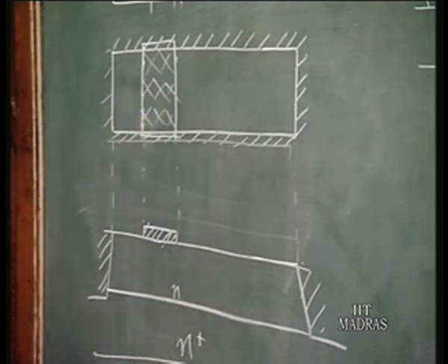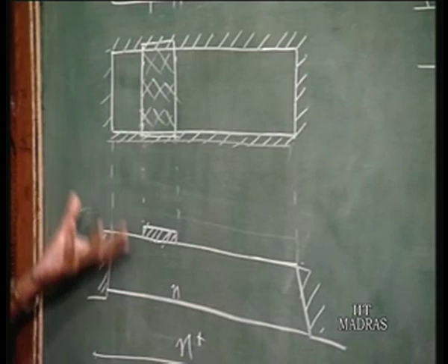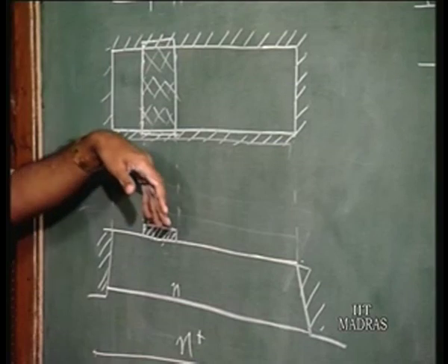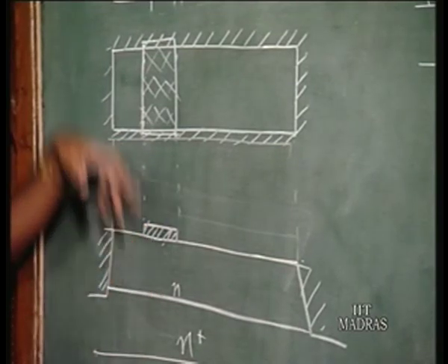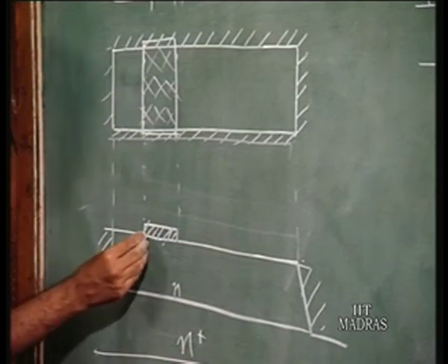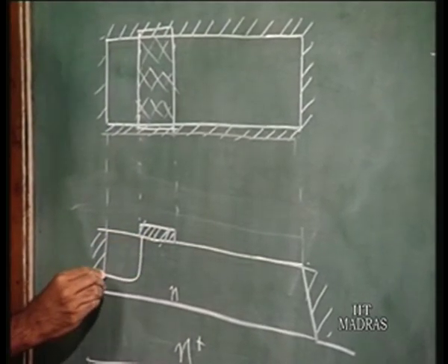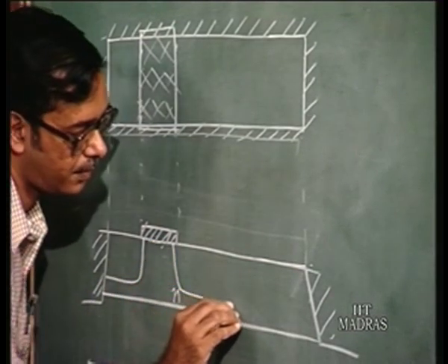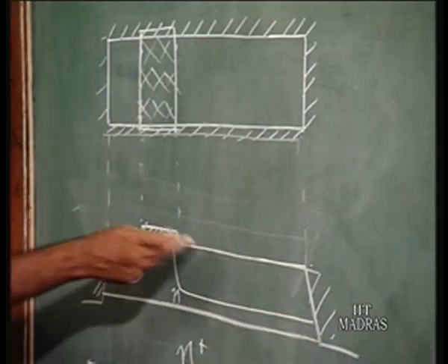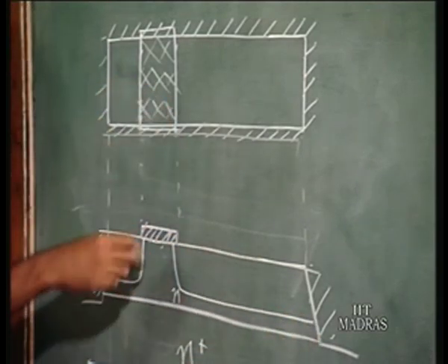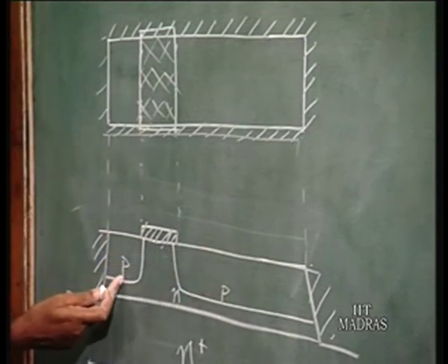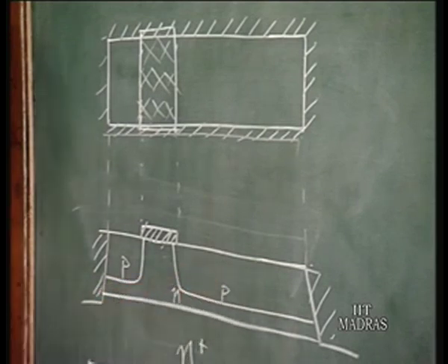Then what you do is boron diffusion, or basically implantation is done, boron implantation through this mask. Here silicon dioxide protects this region when you do an implantation. So what you have is a p region here, and another p region here. These are the exposed regions. So this is a p and this is the p. You can identify that this is for the injector p diffusion and this is the base region for the NPN transistors. All right. So this is done.